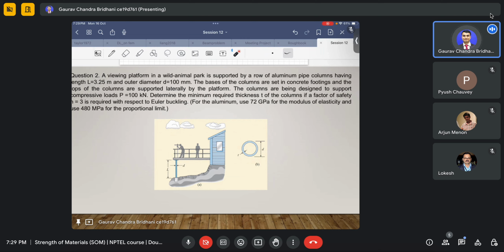But if everything is ideal, if there is no defect and no eccentricity, so everything is perfect, then in that case it can buckle in any direction. Even if you apply the maths, as I told you initially, there is something called small n, which is the mode number, and from that there is a corresponding equation of the shape of the deflected or buckled curve.